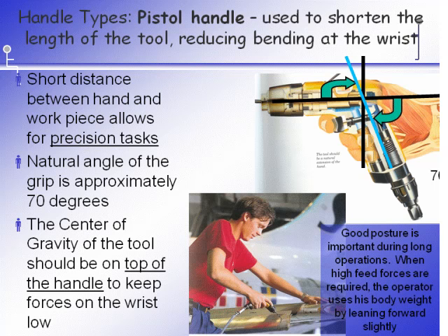Okay, so this shows that pistol grip tools are really good when you have a short distance between the point of application and the point of the tool. Otherwise, they're very hard to use. For example, if you have a really long drill bit on a really short pistol grip tool, it becomes much more difficult to use.